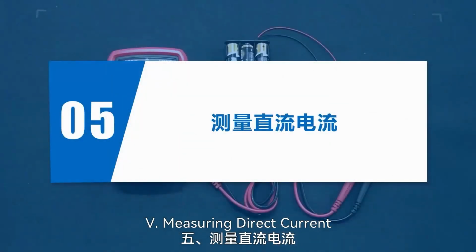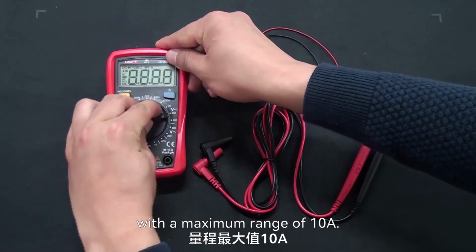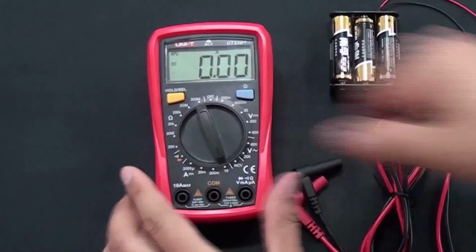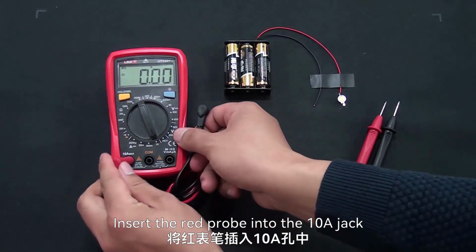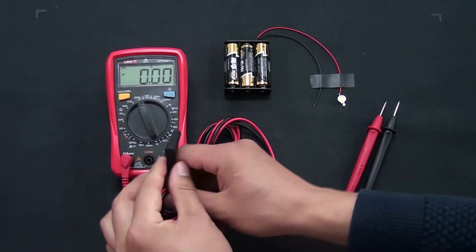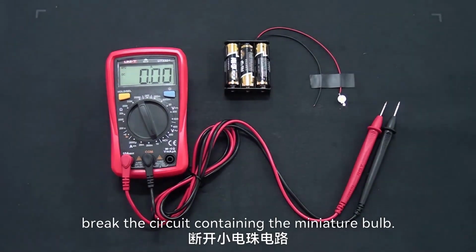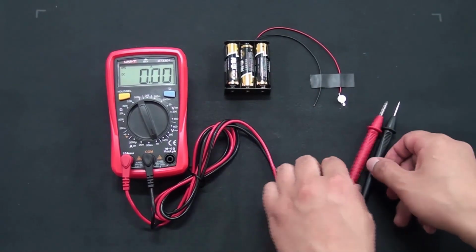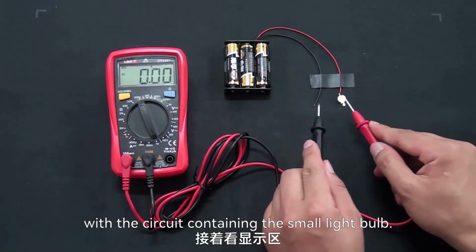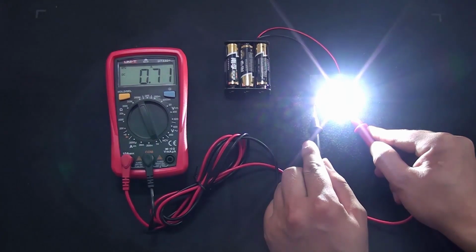Five. Measuring direct current. Select the current range with a maximum range of 10 amperes. Insert the red probe into the 10A jack and the black probe into the COM jack. First, break the circuit containing the miniature bulb. Connect the red and black probes in series with the circuit containing the small light bulb. Read the displayed value on the screen.